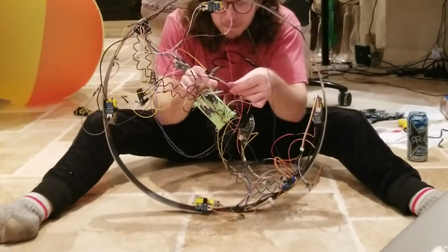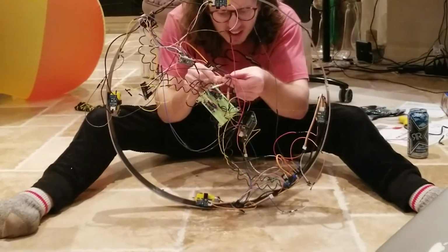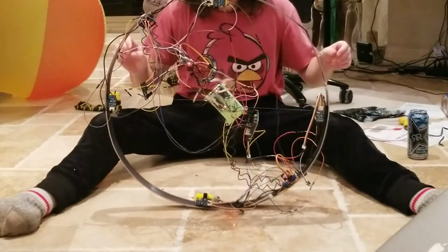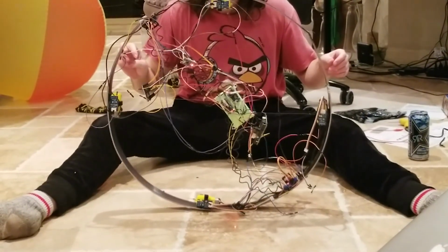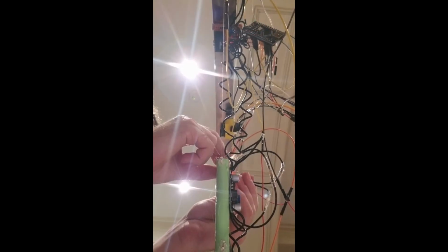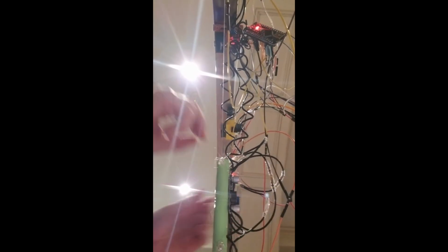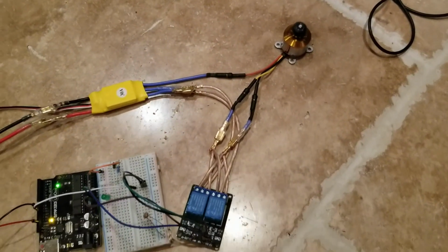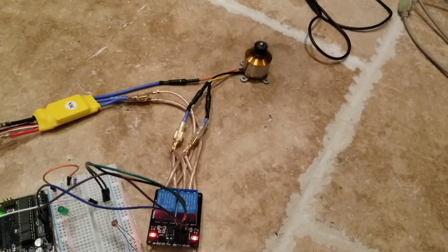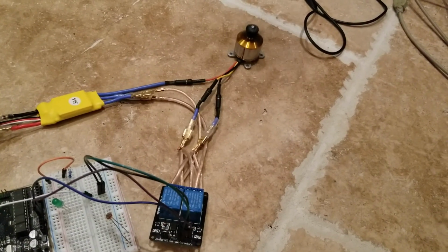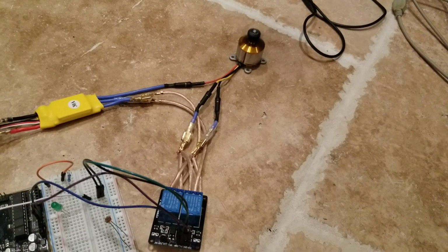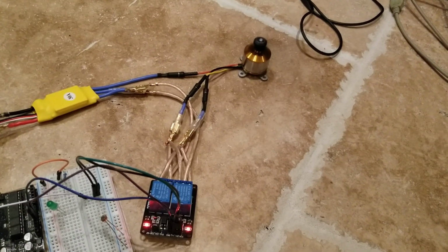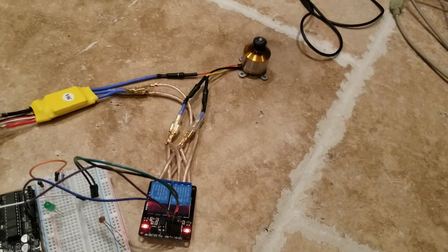There were several reasons why the device didn't work as expected. The noise of the sensors was the biggest issue. Under the torque of the weight of the battery, the noise on the sensors really messed with all the algorithms tracking motion. It was almost impossible to work around this. Another interesting development was learning how to change a unidirectional ESC into a bidirectional ESC by using a relay to switch around two of the phases to the brushless motor.